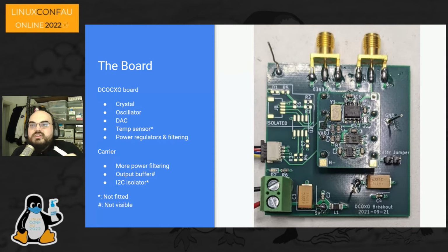But it turns out breadboards are so terrible that they actually invalidated a bunch of my results. So I ended up designing my own board. And I'll make it clear, I didn't do any effort at signal integrity on this board. It is quick traces, everything just chucked where I wanted for quick layout. And it is massively better than the original board.